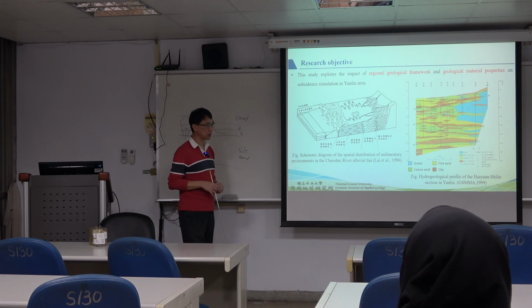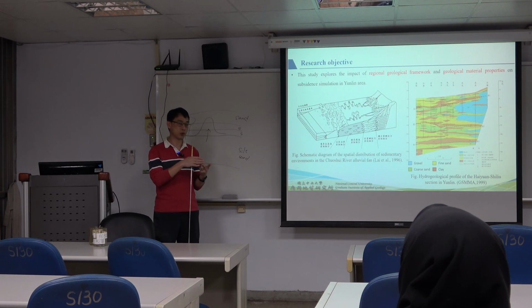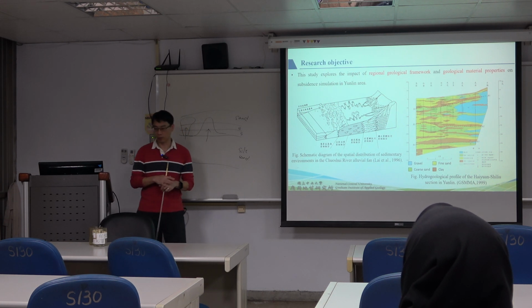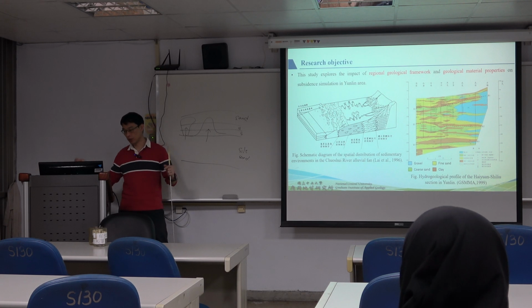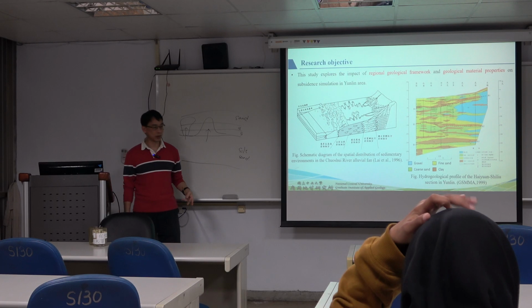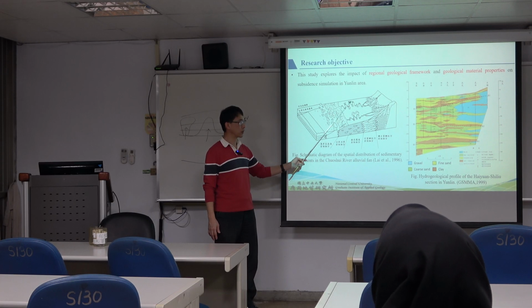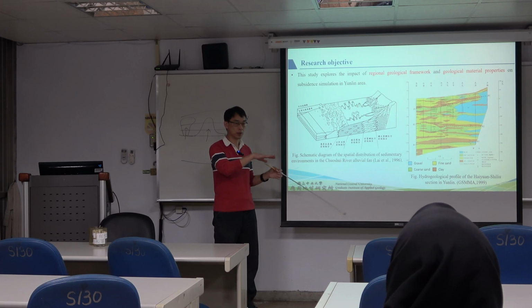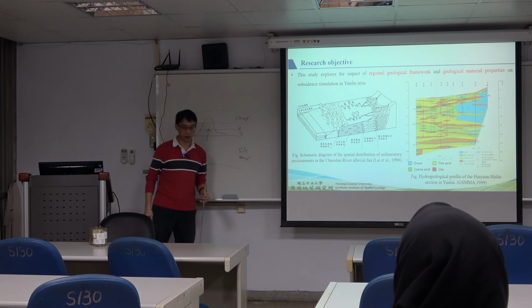Because the Water Resources Agency in the past only used the aquifer and aquitard, as I mentioned previously. They only used these two kinds of layers in a relatively ideal aquifer-aquitard system. They do not have lenses or segments; they just continuously have aquifer and aquitard. But commonly the systems are not like that. They will be relatively compressed, like these kinds of river channels. You can see that they might have some additional river channels, and the deposit will become more heterogeneous. They will not have a uniform layer system. They could be like discrete materials there.